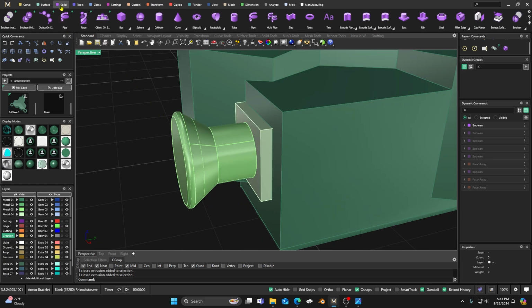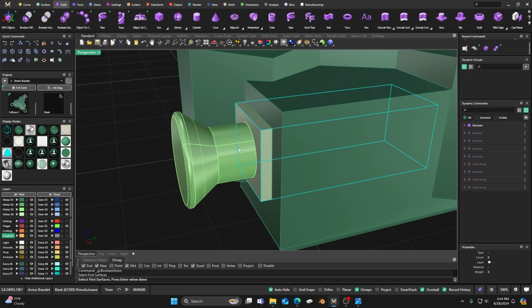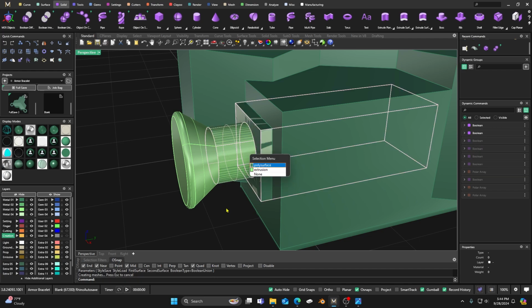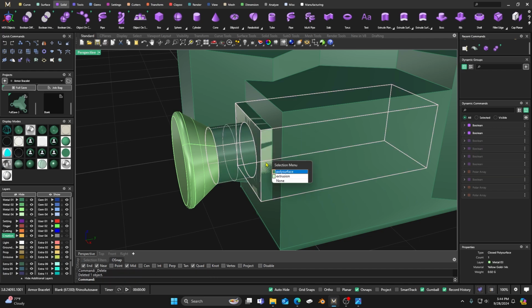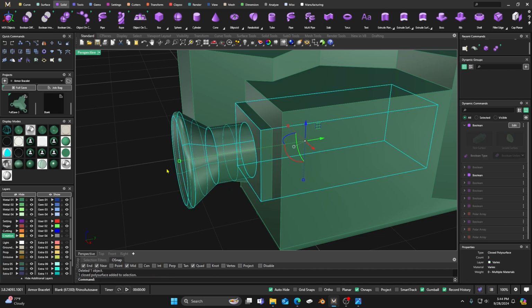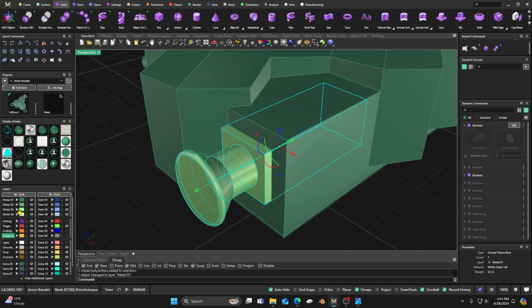Now we'll go to our solids, scroll here, we'll go to Boolean Union. We'll take this and enter, and this surface, enter, and just delete that one. And I'll just Boolean Union again for this surface here, enter, this surface here, enter, and then we'll just delete that one there. So we have this piece here, right? Okay, so we'll take that and we'll change it to here.